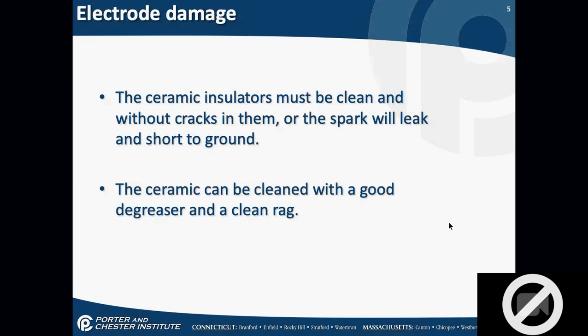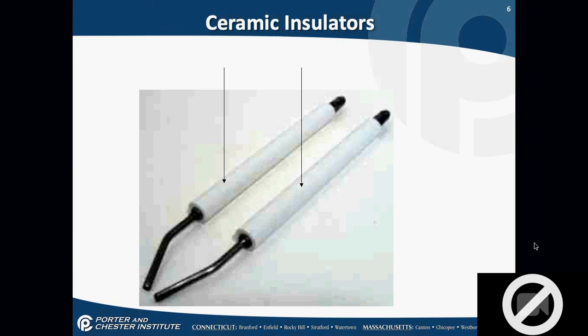If this burner is maintained regularly on a yearly basis, you don't have to use major things like sandpaper and everything else to get the electrode ceramics clean. The best degreaser that I've ever found for cleaning electrodes and nozzles and nozzle assemblies, believe it or not, is lacquer thinner. You can buy it in the paint aisle of Home Depot or Lowe's. Lacquer thinner is probably the best cleaner I've ever found to remove the garbage from this.